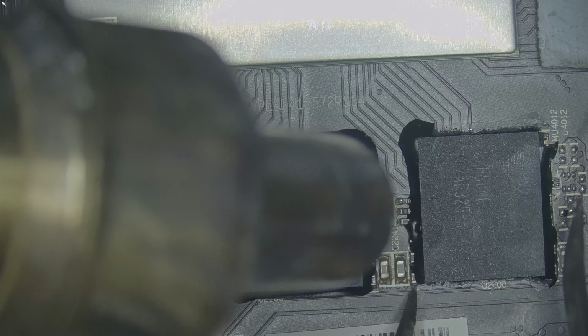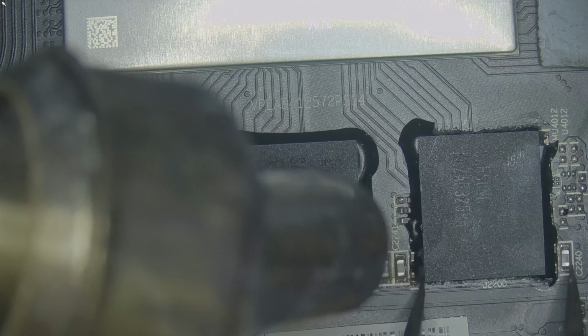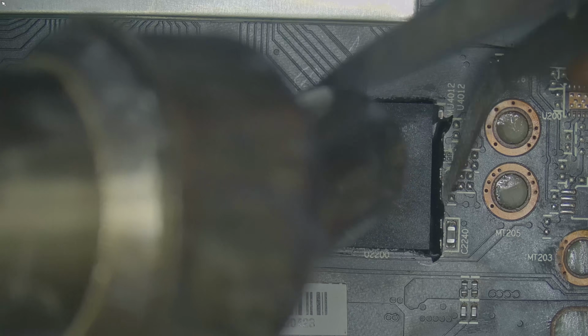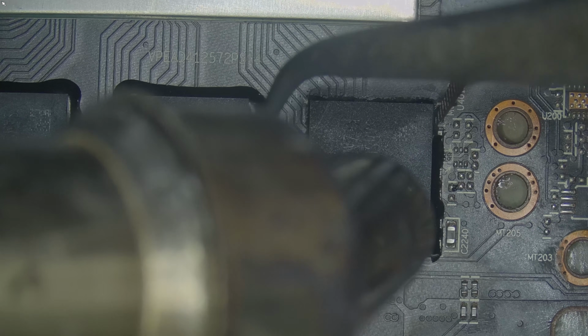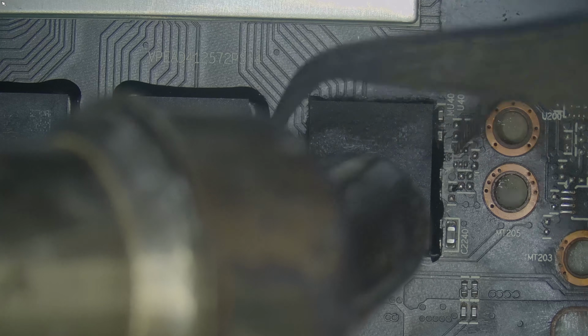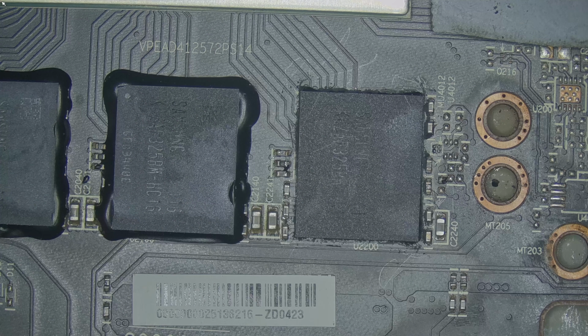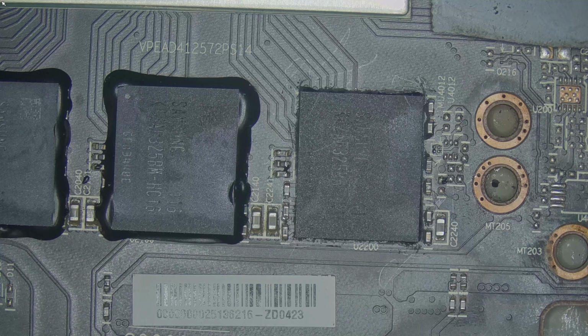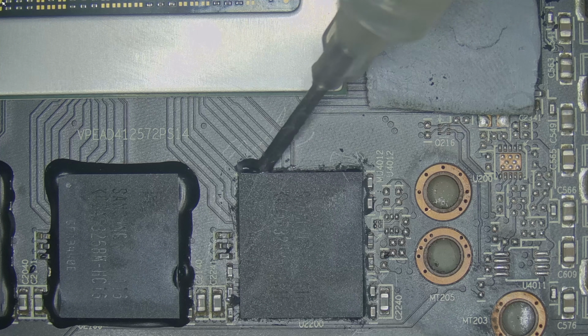The first step is to carefully remove as much of this epoxy as possible. To do this, I apply some heat to soften it. At the same time, I need to be very careful because there are tiny SMD components all around the memory. As you can see, I managed to clear away some of the epoxy without damaging the surrounding capacitors. Now, for the actual chip removal,